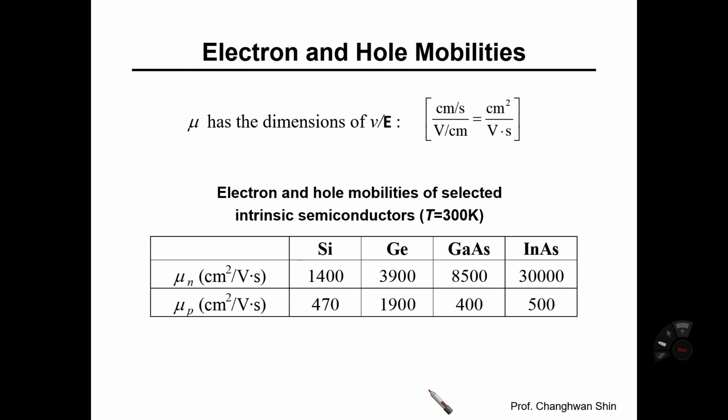That's the reason why gallium arsenide is widely adopted in industry for high-speed integrated circuit applications. Why high speed? Because the mobility of electrons is super good, 5 times higher than the mobility of electrons in silicon. So the innovation of using different materials is always associated with the mobilities of electrons and holes, and that is associated with the operating frequency of the circuit system.